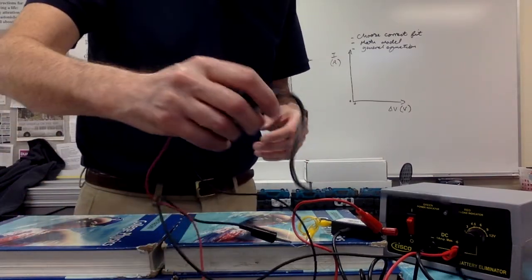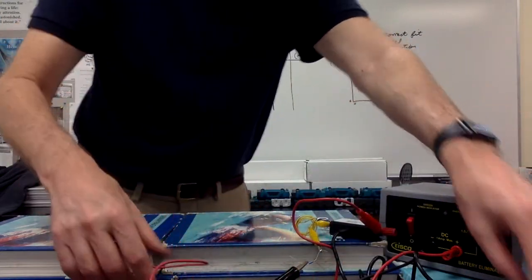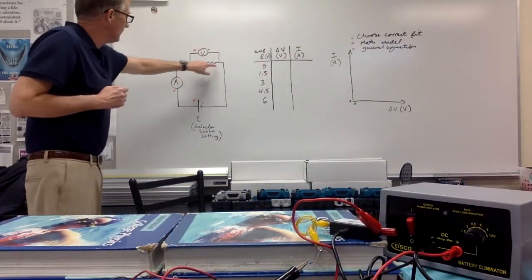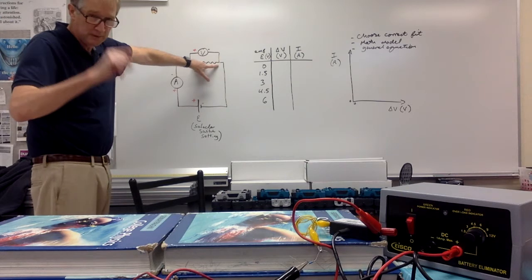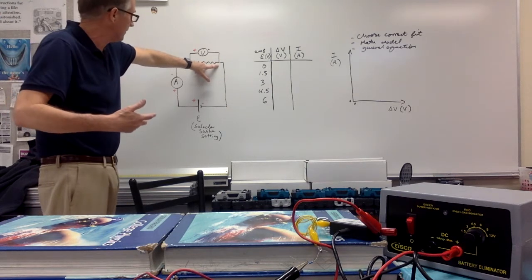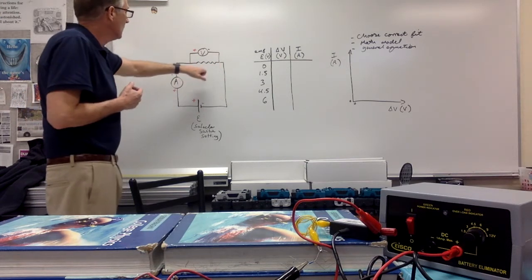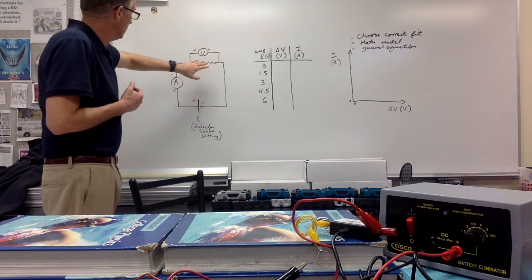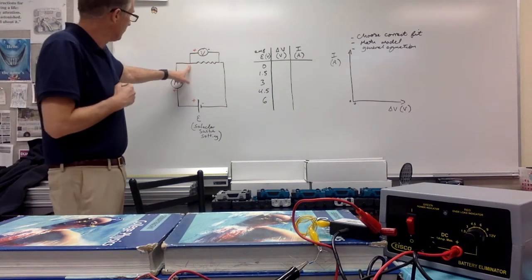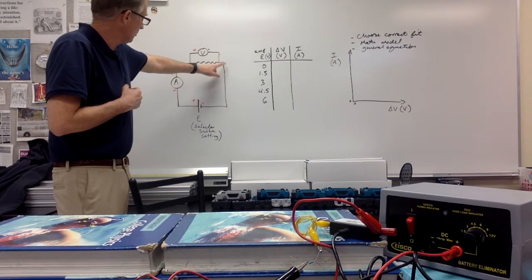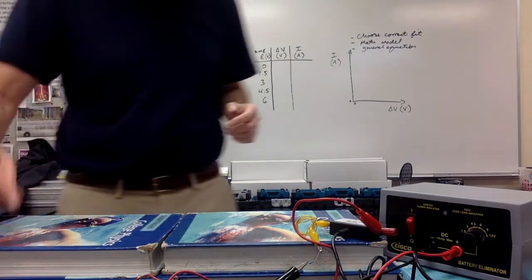Then the last thing I'm going to do is connect the voltmeter. Voltmeters, remember, just measure to see if there's any energy usage between here and here. If there was no energy usage, this would read 0 because that would be at the same energy level, the same potential. If there's any difference between this point and here, then energy either got used up or got added to. In this case, of course, it's going to use up the energy, so there will be a difference between these 2 points once I turn it on. I put the positive terminal on this side and the negative terminal on this side, because polarity matters, and this is going to measure any potential difference.